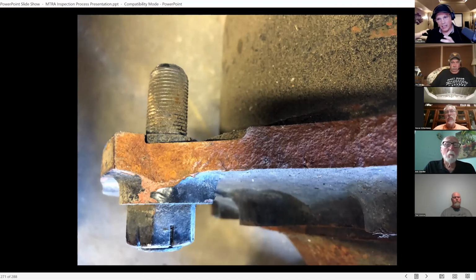You've got this really heavy wheel, tire, and hub assembly. You've got the planet gears and everything, and it's held on by this really thin piece that, whenever you have a corner, is a failure point. Usually things tend to be tapered, for whatever reason. You're talking about a 1950s design. The original Clark hubs are a pretty old design. That's why on the newer reproduction CRD hubs, the material is thicker or the tapers are different, and they actually have webbing on the backside to keep those from failing.